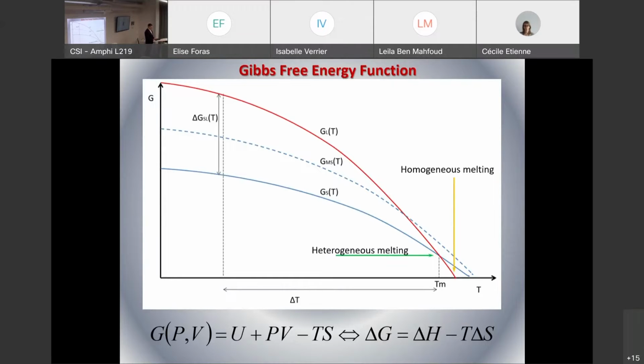However, in reality, it never happens at this point, because in order to develop a new phase, one has to add even more energy, so that a nucleus of the new phase must appear and then grow, overcoming the nucleation barrier. Depending on the presence of nucleation sites, which can be, for example, a surface or defects, the difference between the Gibbs free energy of liquid and solid at which we have the phase transformation is different. If we don't have any nucleation centers, then this Gibbs free energy difference may be significant.